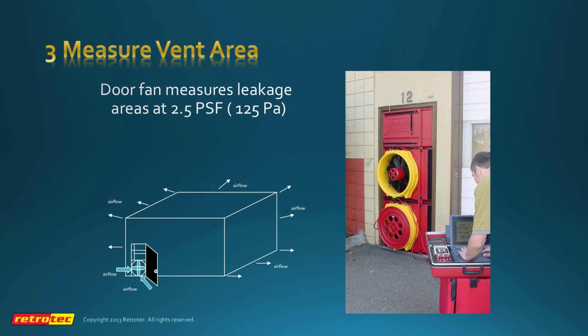Some of the manufacturer's free vent area is true as long as the pressure is up to a very, very high value. So what I do if I'm using a vent, I take it and I slap it in a cardboard box and pull the negative pressure on it, because you don't want to blow air at the vent itself. And I negatively pressurize the vent up to, let's say, 100 pascals, and I see how open it is. Then pressurize it to 200 pascals and see how open that vent is.